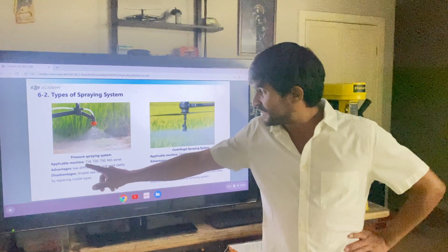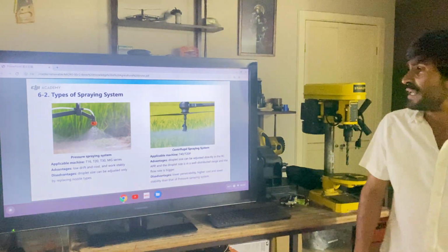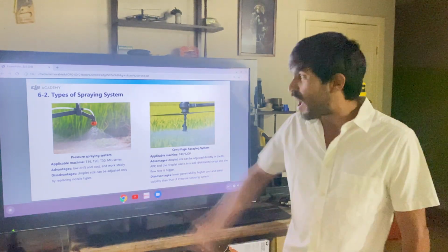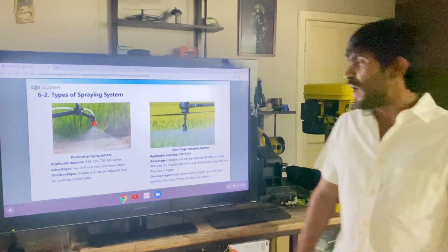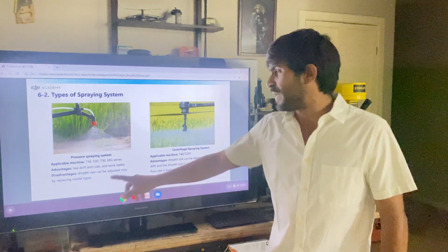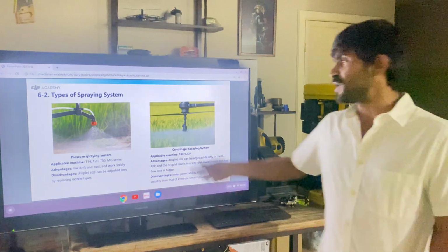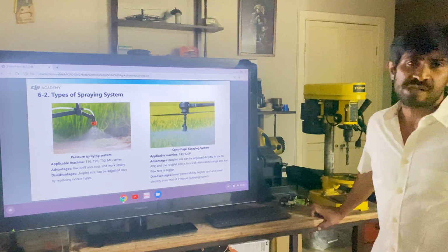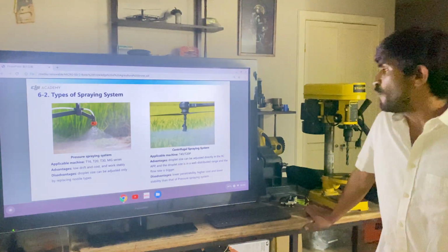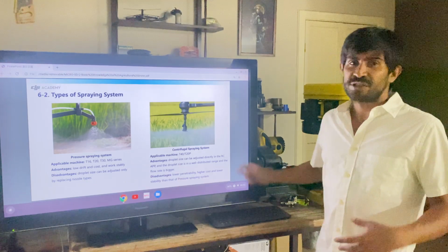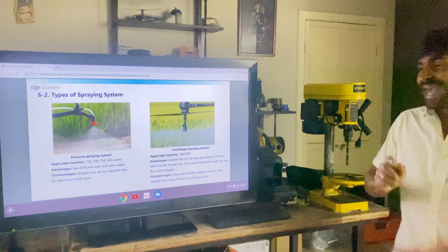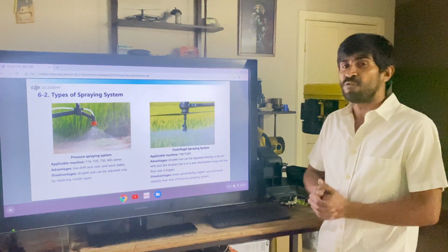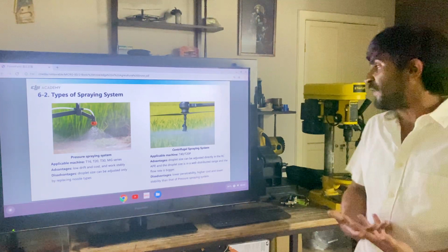In the T16, T20, T30, we had these pressure nozzles, which were low drift, low cost, low maintenance, highly stable, but the problem is that droplet size couldn't be adjusted in flight. You can only change droplet size by actually changing the nozzles. Whereas with the new centrifugal spraying system, with the T40 and the T20P, the droplet size can be adjusted directly from the remote control app, in the middle of a mission, as a function of wind conditions, as the pilot sees fit.